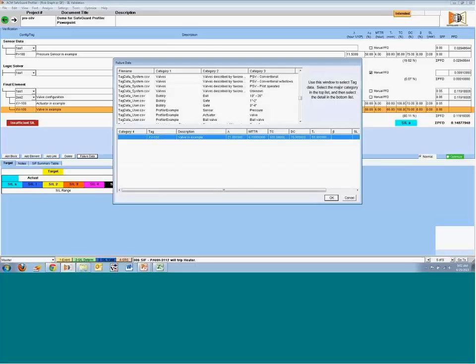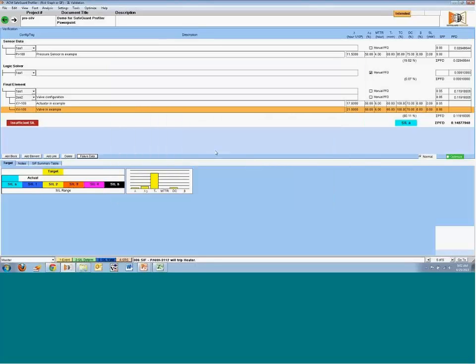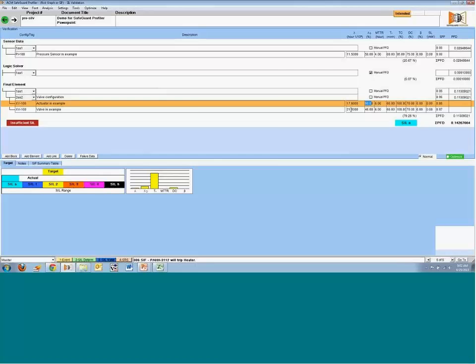Okay, our valve, and that's going to enter in all the information we need there. If I wanted to update some of these values, I certainly could. At this point, there's nothing keeping me from doing that. It won't let me put in a value that's non-existent. And what we get at the end is our probability of failure on demand, which is going to be that same value I calculated back in the PowerPoint.